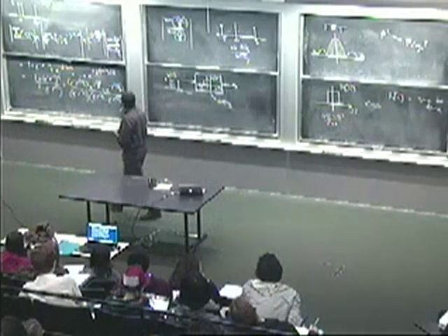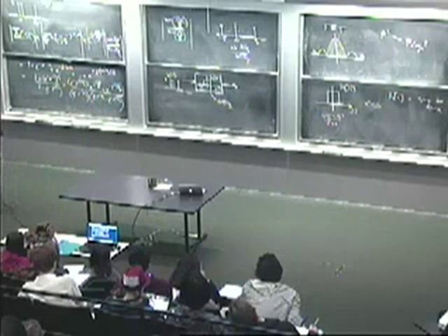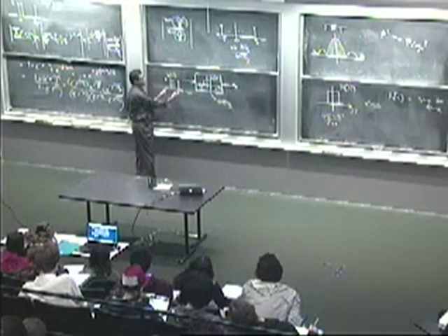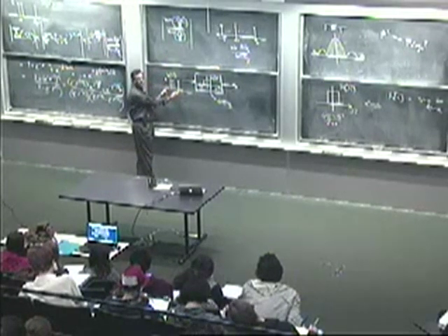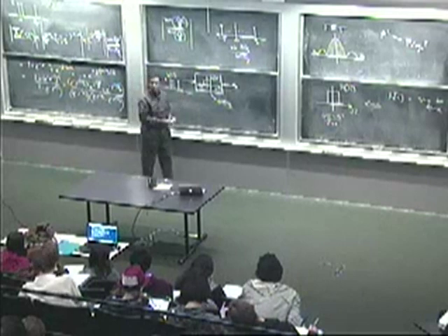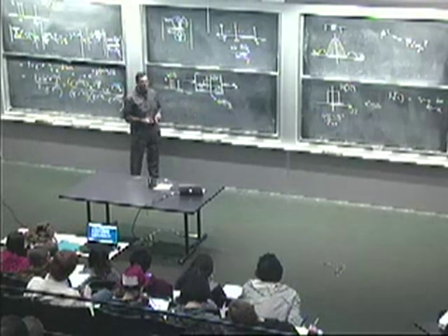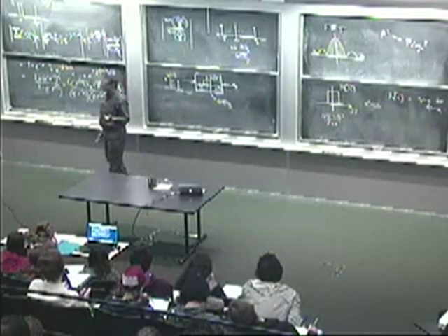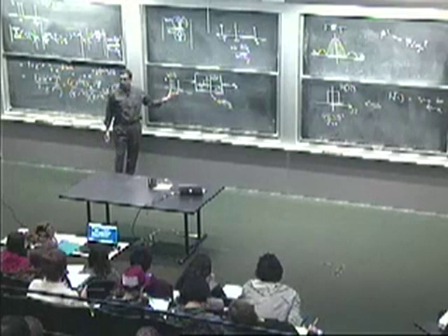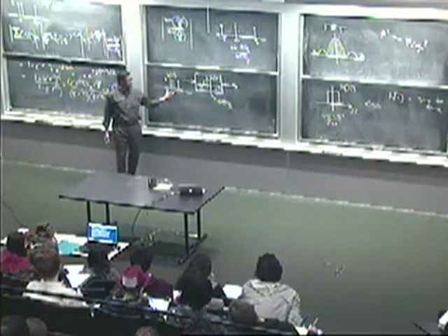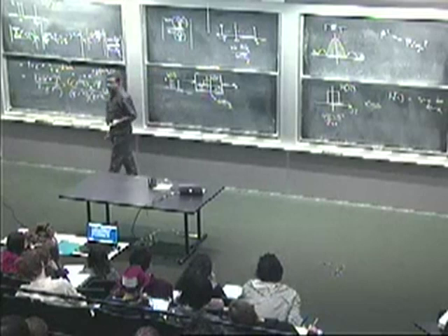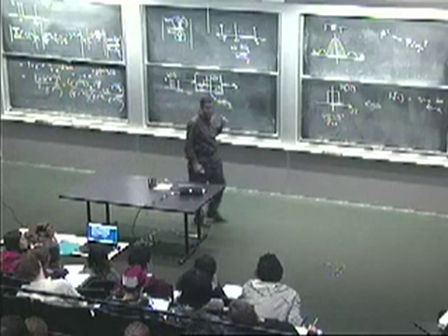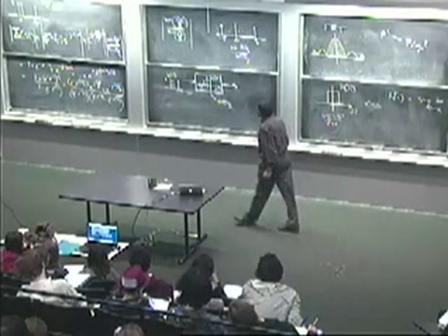Now, how might you get a better defined pulse for a given channel? So if I gave you this channel, we sent in this pulse of length 256 samples, and we got something that we didn't like because it spilled over into other slots. The reason it spilled into other slots is we were cutting out too much of its spectral content. What could you do to this pulse to get more of its energy across that low-pass channel? Yeah? Sorry? Set a longer pulse. How does that work now?